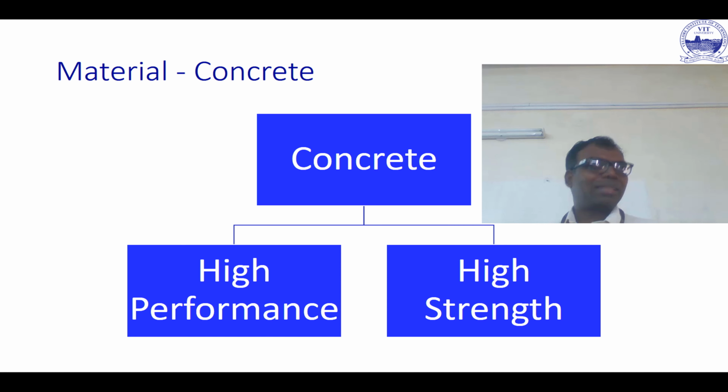Again, you choose the aggregates in a manner that creep is reduced. The creep is a function of the aggregate. Okay, what is creep? Creep is the time dependent deformation of concrete. Okay, so essentially it will shrink. Now you want concrete and steel to have very good strain compatibility. So if suppose you find that there is a small reduction in the length of the member, the strain reduces, and proportionally the stress of the bar or the tendon reduces, which in turn reduces the pre-stressing force which you have applied.